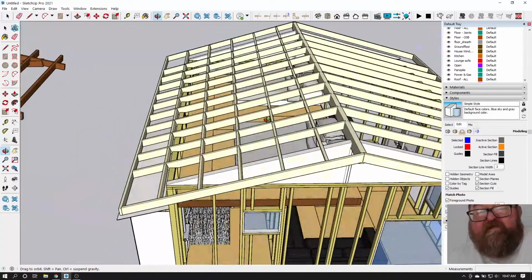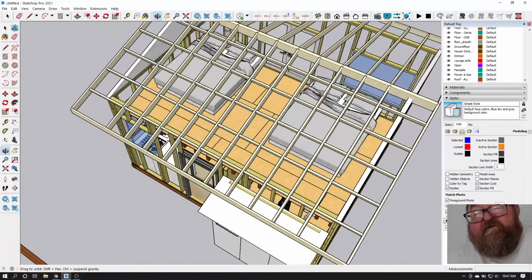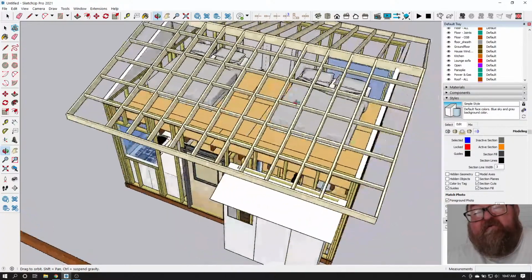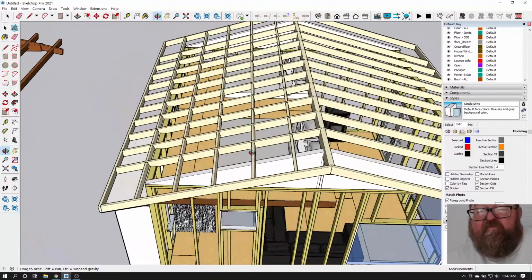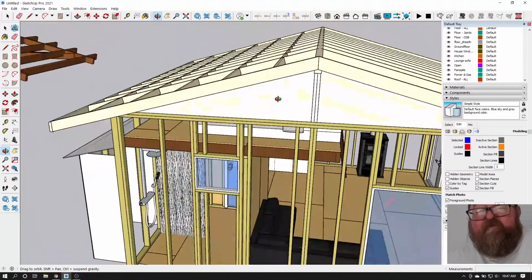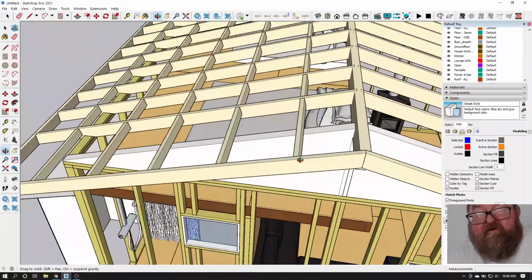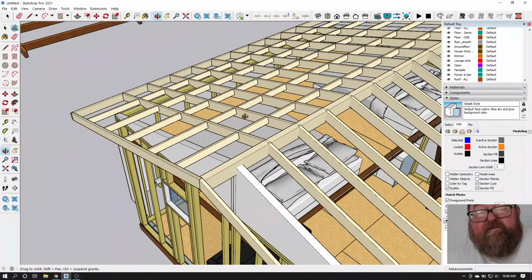Now the spacing of the rafters depends on what size rafters you use, how thick they are, how wide they are. If maybe they're spread out a little more, and maybe this is spread out a little more. But the point is, you took care of your structure first, okay? And the way you did that was with this magic ridge beam, right? And your overhang is going to be really strong because you're cantilevering this thing that becomes your coffer in here.